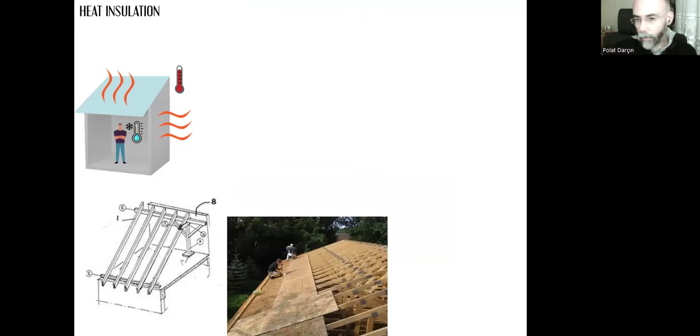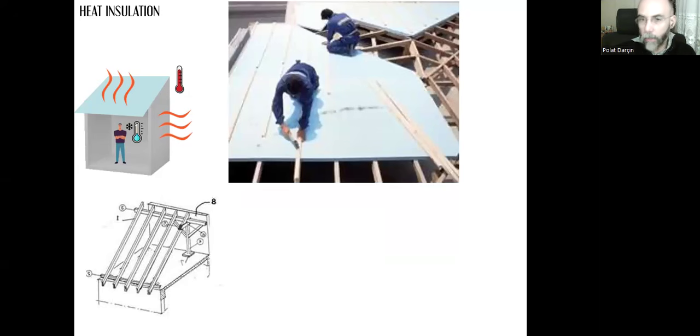The third option can be using plastic substances, but maybe these XPS or EPS boards can be enhanced in terms of fire resistance. And you remember that we covered engineered wood panels over the rafters for a smooth surface. Instead of these engineered panels, we can use heat insulation panels.